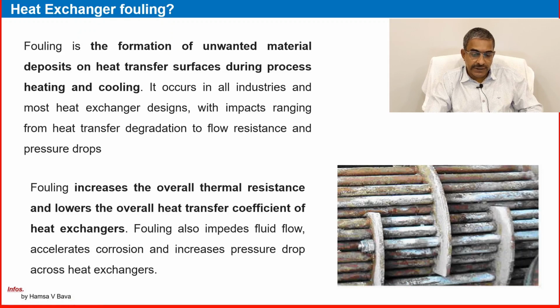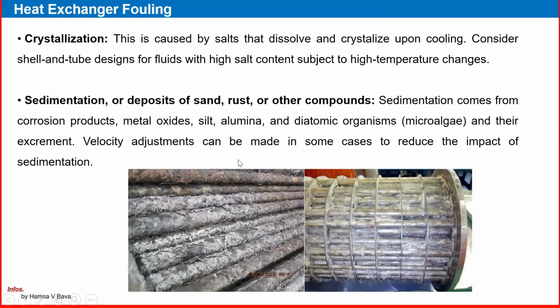Fouling also impedes fluid flow, accelerates corrosion and increases pressure drop across the heat exchanger. So, types of fouling: crystallization fouling is one type. This is caused by salt that dissolves and crystallizes upon cooling. Consider shell and tube designs for fluid with high salt content subject to high temperature changes.